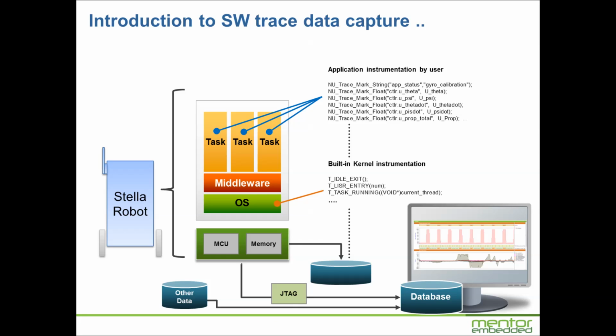Another important point to mention here is that the Mentor Embedded Sourcery Analyzer is really an open-ended platform that enables users to import any type of data into its database and perform visualization and analysis of the data. It is not tied to Nucleus software runtime in any way. So we could possibly envision a system where data comes in to the host side from external sources as well. For example, if we have some kind of external data acquisition device that is capable of measuring real-world variables such as analog voltages, current, etc., we can put together a system where one would be able to visualize software runtime and the real-world variables all within a unified time frame, as long as we have mechanisms in place to synchronize the time bases between the embedded target and the external data acquisition device.